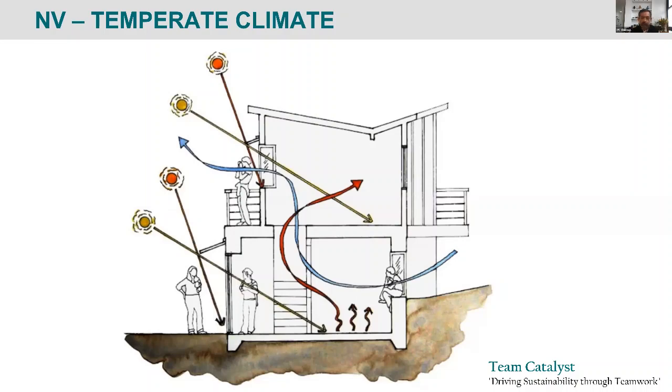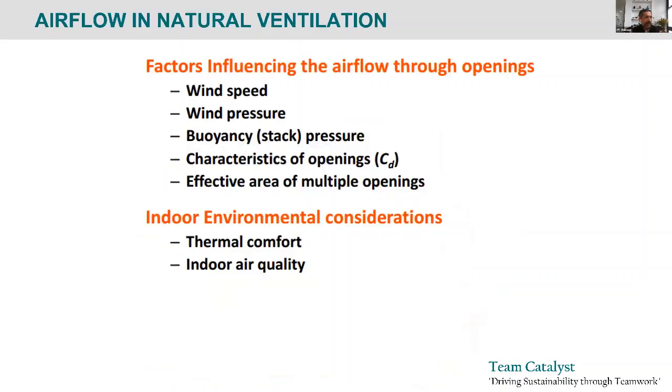So you want to encourage the sun to come into the space in winter. You want to keep the sun away from the facade in the summer. You want to allow the breeze to find its way in the summer when temperature conditions are cool, and then you've got to balance these strategies so that across the year they work to give you the best outcome. Okay, and then you might need to supplement that with a little bit of heating and cooling to make life bearable. So how do you do that in DesignBuilder?